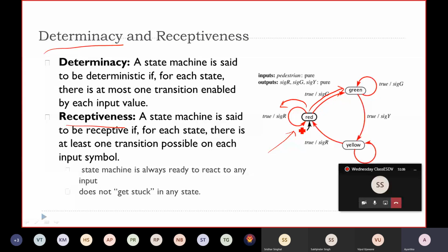Because in case of this system itself, if you do not define those timing requirements, time-based triggering, in your FSM design, then your FSM actually becomes non-deterministic, where you don't know whether from red you will make a transition to green, or green to yellow, whatever it may be, or you will retain your existing state, maybe red, green or yellow.